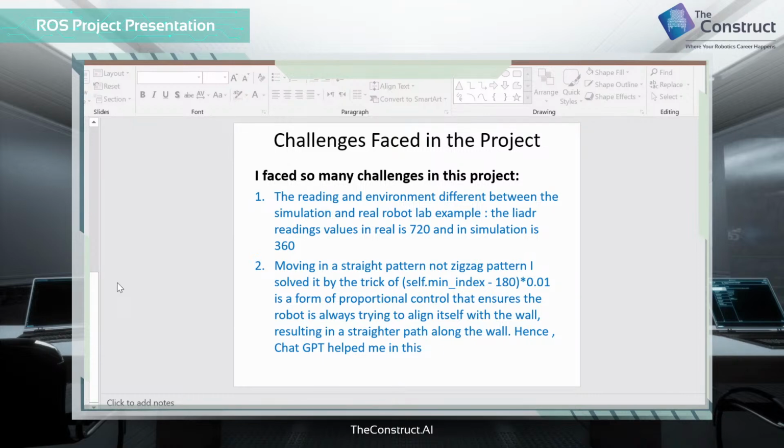In ROS2, you get a blocking situation, just think about it, because of the structure of ROS2. This way you can now work with separate callbacks doing different things to manage different sensors. Because if you have many subscribers, you'll have many callbacks. Let's say you have a sensor for your odometry, because you probably do in your action server. Then you run that callback within another callback inside your main action server.